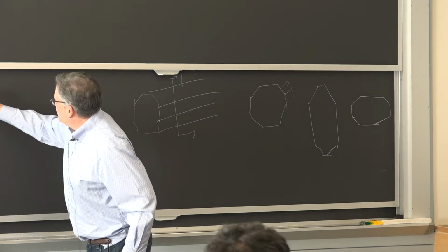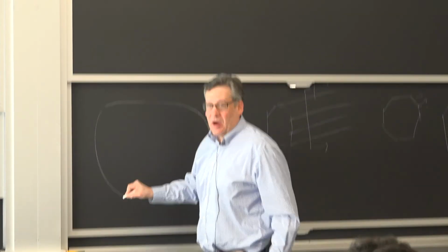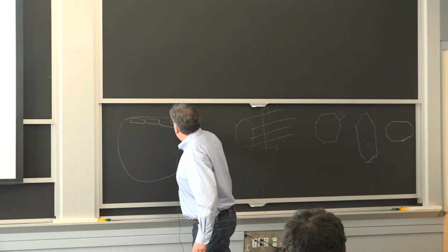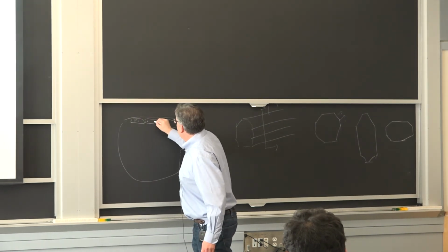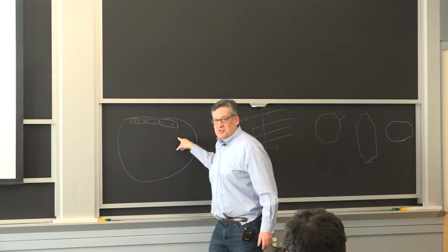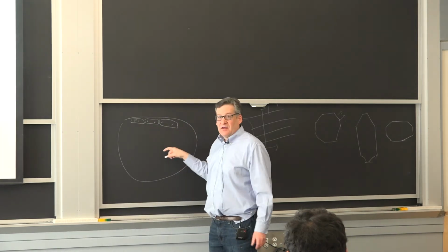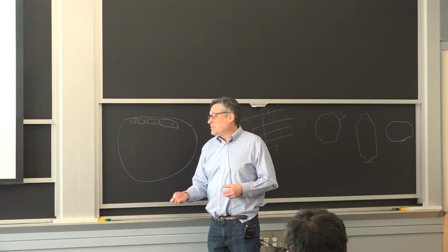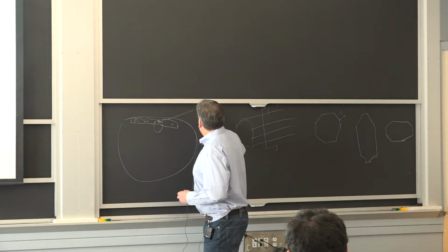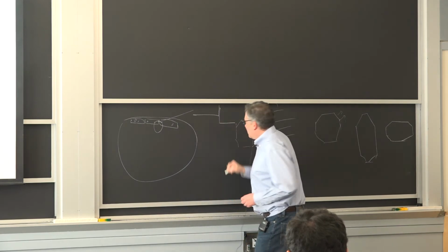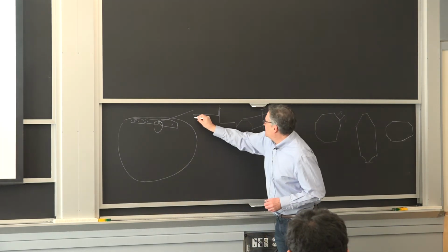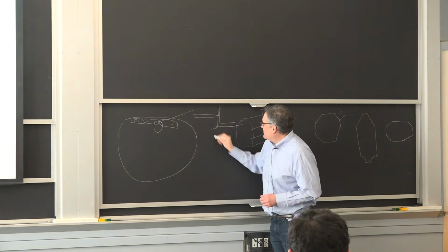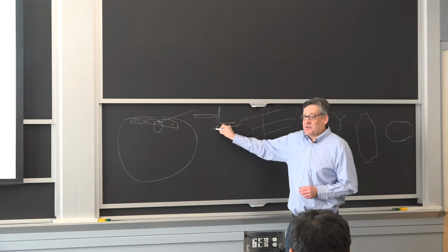So the trim, like I said, you've got some trim die that's trimming out some part. And they have these little inserts that they bolt on actually on the side. This does the actual trimming. This is the actual cutting surface right here. And they make them removable so they can replace them when they wear out. But the problem is that sometimes they're not exactly lined up very well. And so the steel gets trimmed like that. And of course, right here, you've got an invitation for a crack. And I've seen this happen, actually.